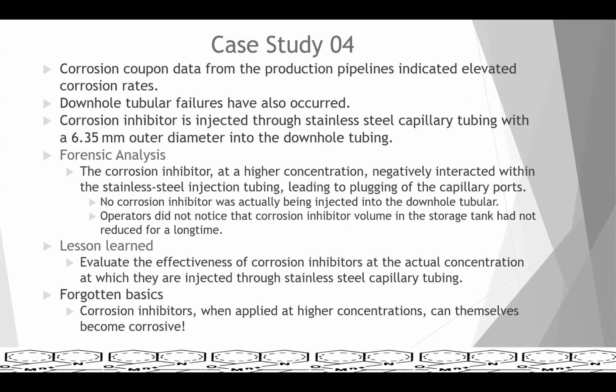So this case study also reminded us of the forgotten basics. Corrosion inhibitors, which are chemicals, some chemicals, when applied at higher concentrations, can themselves become corrosive. So if you are applying corrosion inhibitor at a particular concentration, you better do the lab testing at those concentrations.